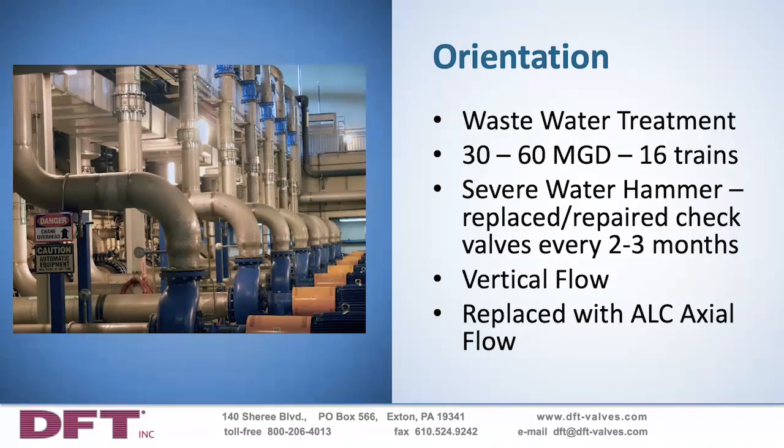Here we're looking at a wastewater treatment plant, 30 to 60 million gallons per day. There were 16 trains in this system. They were having severe water hammer, and they were replacing and repairing check valves every 2 to 3 months. It is a vertical flow application, and we replaced those valves with the ALC axial flow valves. There was some modification required to get the correct face-to-face dimension, because the ALC is a narrow face-to-face pattern, but the axial flow ALC valve solved the problems, and the customer is very happy with the outcome.